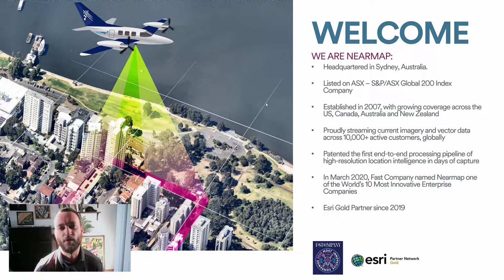And what that means for engineers is that this can be used to conduct not only more of a data analytics focus of doing feature counts and quantity assessments very quickly and in an on-demand fashion, but also doing things like generating CAD line work, right? Since all this data is defined as points, lines, and polygons, it can very easily be formatted into things like drawings that can be overlaid on top of our imagery and give your engineers a way to jump quickly into project design. And I'm going to be showing examples of all of this a little bit later.